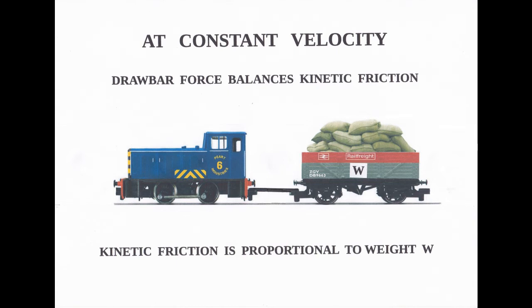Let us imagine that at rest we supply the motor with a modest voltage. This will cause a modest stall torque and force via the drawbar. The force will have to overcome static friction, but once underway only kinetic friction. Both will depend on the weight and the coefficient of friction, which will be less if the truck has ball races rather than plain bearings.